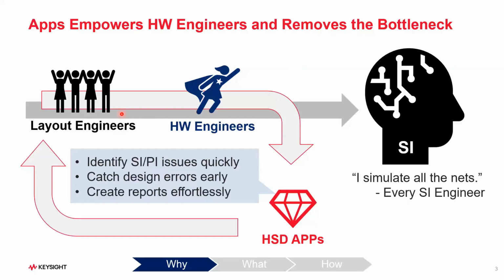So this is the data you get based on the standard, like PCIe Gen 4 has one set of impedance match, or insertion loss, return loss should be this much, or Gen 5, or USB 3, or the latest, USB 4. Similarly, if you're working on any basic differential impedance-matched track, you must have this much impedance on this net. So are you following any such kind of guidelines on the layout?